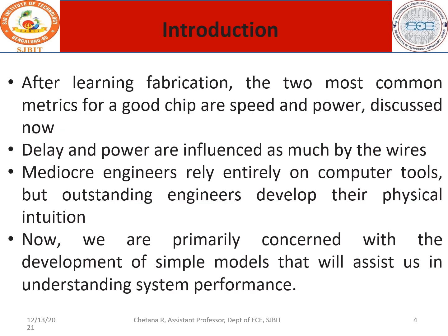Now, as we have already been introduced to the third module, where power and delay are very much important, we'll go into the introduction before beginning. After learning about fabrication, which was dealt with in the first module, the requirements are in terms of speed and power for a good chip. Ultimately you have to have the best of the speed and the power, and these are very much influenced by the wires. Wires are very much used in our design, which will carry the information from input to the output, and at the same time carry power from the mains to the device. So wires play a huge role.